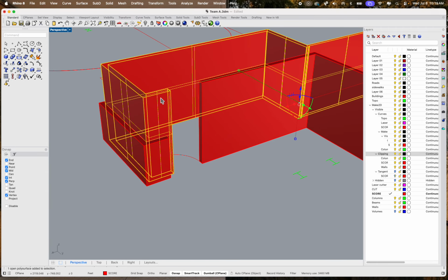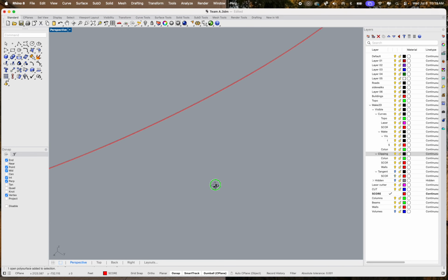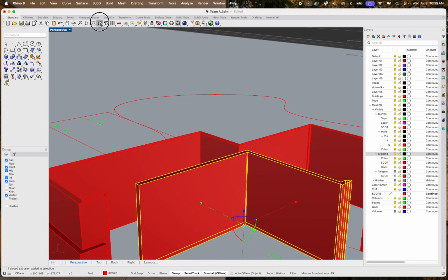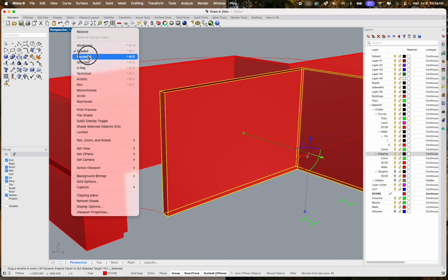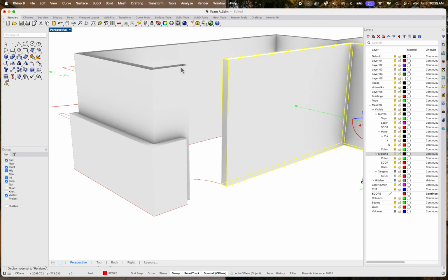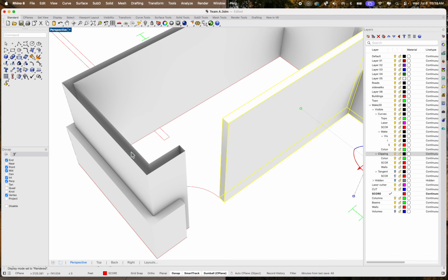Oh, it looks like I needed to close that curve too. Obviously the closed curve one gave us a solid form, but check out what that accidental error did to this wall. And I can't tell you enough, I see this so much in studio. Or we see the wall, but we don't actually have the thickness of the wall. Now that would probably be okay in studio, but for this, we're gonna 3D print it. And we know that we need a closed object. So that ain't gonna work, right?